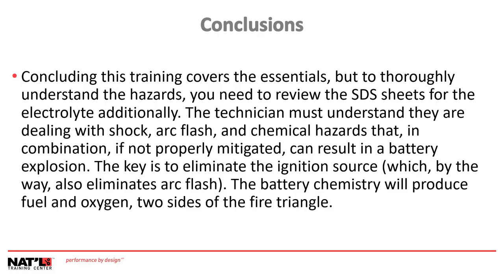The key is to eliminate the ignition source, which by the way also eliminates the arc flash. The battery chemistry will produce fuel and oxygen, two sides of our fire triangle, just simply waiting on heat or a spark.